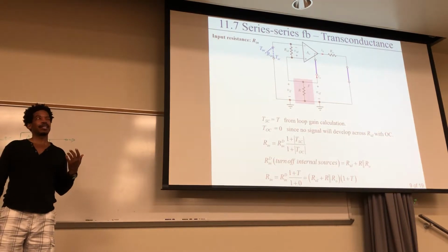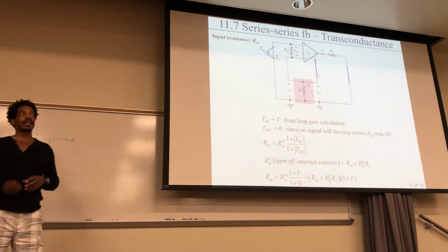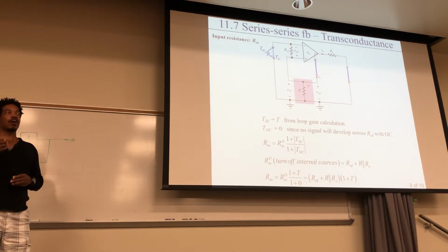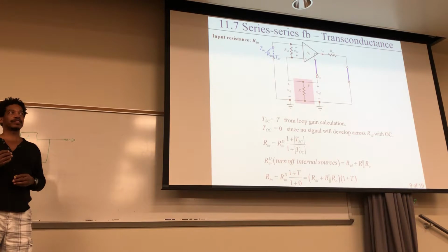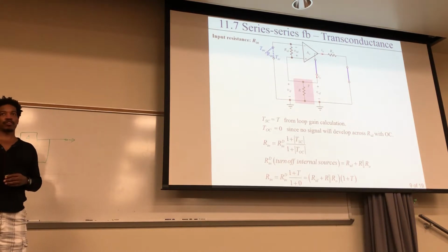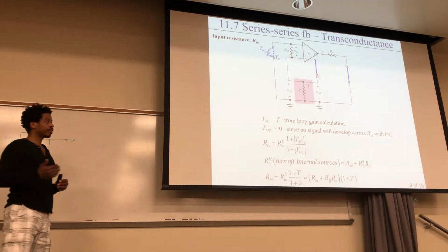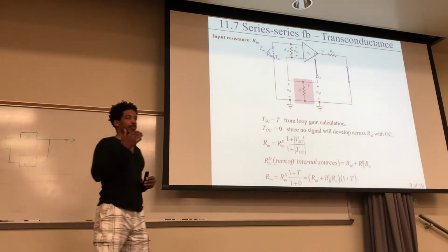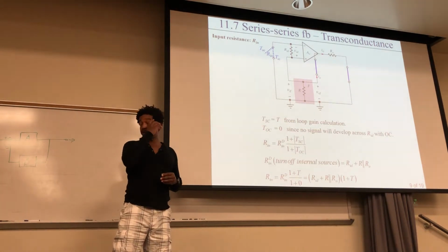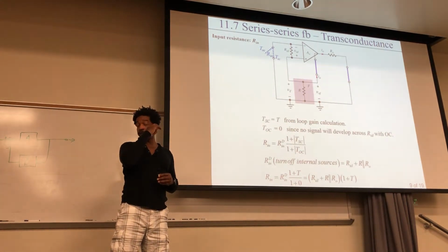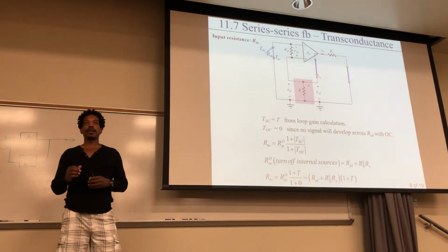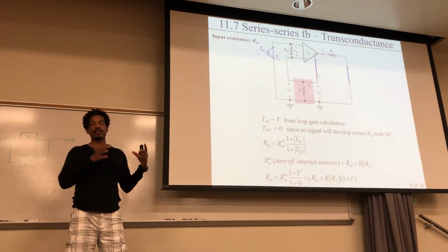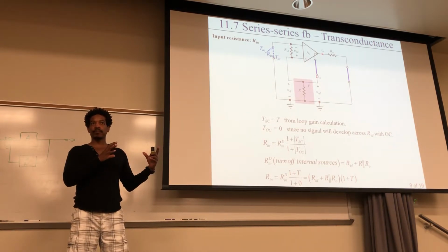Let me put it this way. All of your independent sources are turned off. Your voltage sources become short circuits, but your controlled sources, you leave them alone, okay?